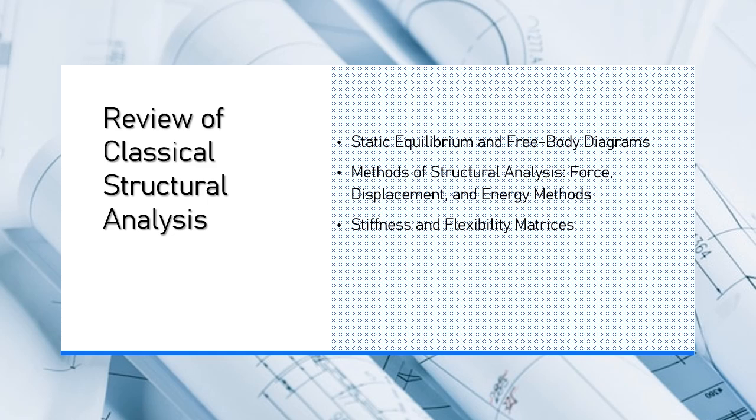Flexibility matrix. Most effective in force-based methods, especially in statically indeterminate structures where the unknowns are internal forces. Suitable for analyzing displacement effects in systems with multiple redundancies, such as structures with complex boundary conditions or supports.